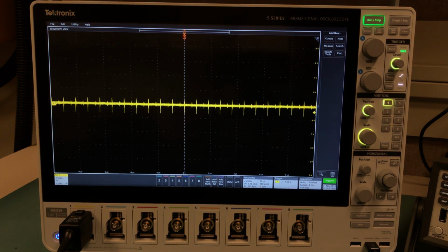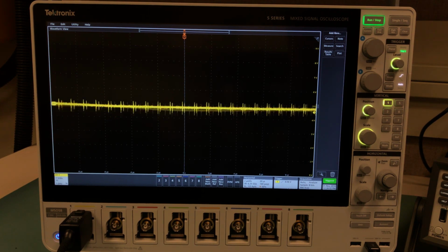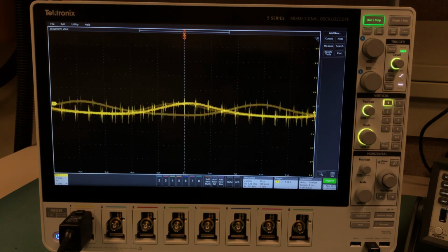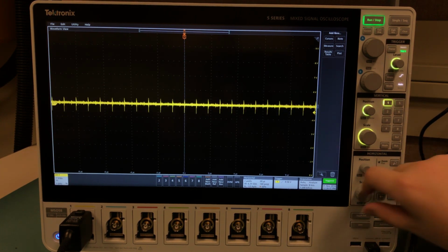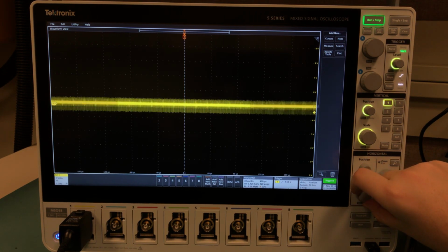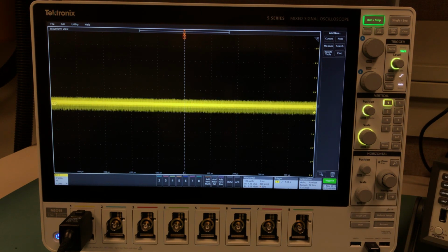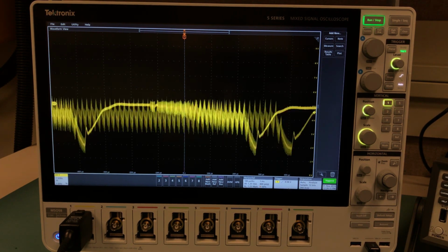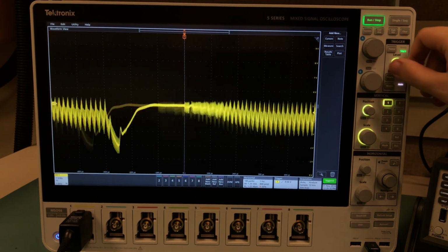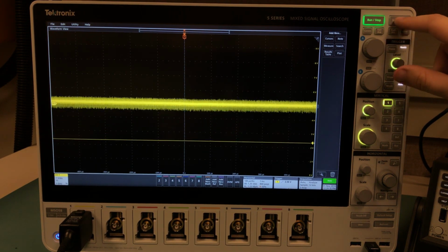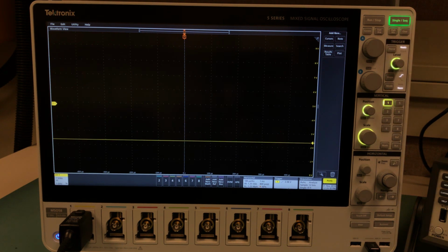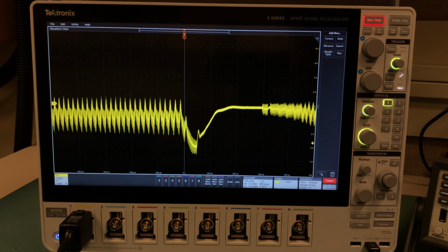As the second SMU sweep happens, these signals look pretty long. I could spend more time using the 5 Series' advanced triggering features, but I think I'll scale out again first to 100 microseconds per division, and then I'll start the SMU sweep again. Well, we can see a bit more noise, and whoa, what was that? I'll move the trigger level and set the 5 Series to capture a single event. I suspect this is the power discontinuity we saw earlier, but even before that we're still seeing 2 volts of